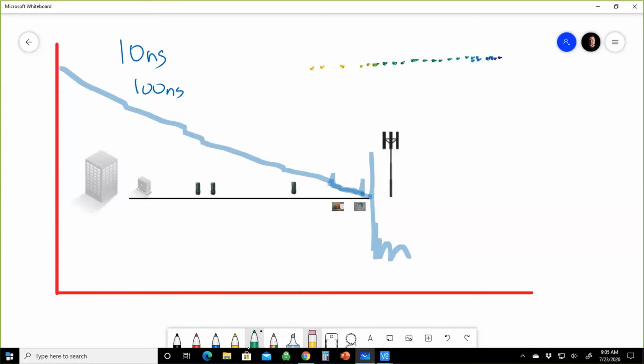And what that means is at 10 nanoseconds, I am sampling the fiber a lot so I can see every single event here. But the downside to that is 10 nanoseconds is very weak. So after, say, 10 miles or so, it drops off into the noise. So now we're not seeing everything. We're not seeing past these 2 splices here mid-span.